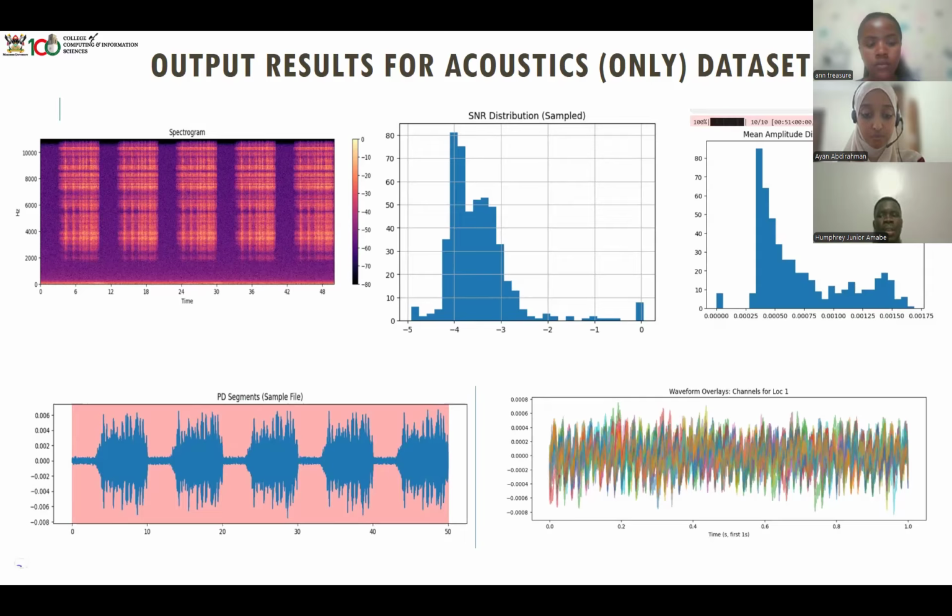These bursts occur at regular intervals, which physically characterizes PD activity. The spectrogram is our first clue that there are hidden structures in raw audio. The different PD types have different frequency signatures, and this visual tells us acoustic features allow us to discriminate the different types of PD.